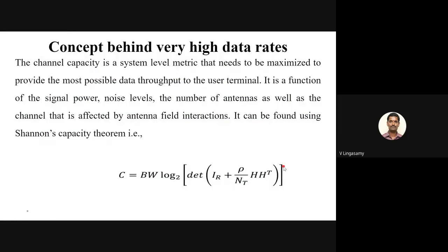Now we were talking about high speed, latency, many things, right? Mainly high speed. Whenever we talk of 5G, we say we're going to give a very high speed. So how is it possible? Throughput, or capacity, depends upon many factors. One is bandwidth, right? Operating bandwidth-wise, we are going up to 400 megahertz, but occupied bandwidth will be somewhere around 200 megahertz. So we got plenty of bandwidth now for 5G, but in 3G we had 5 megahertz, and in LTE we had 20 megahertz, right?